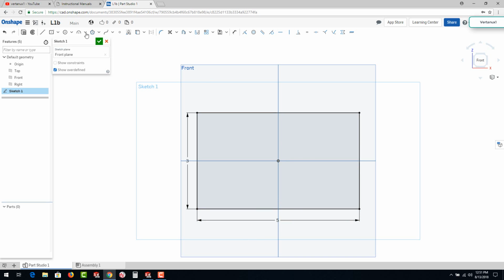Okay, now with this, we're going to go ahead and put the holes in. So draw a circle here, go to the circle right about there, click, and that's going to be 0.5. And then let's locate it 3/4 of an inch off of each edge. So we'll go over here, select the center point to the top edge. Let's get the center point again. I must have missed it. There we go. And get it between the points there. And let's go ahead and put in 0.5, actually 0.75.